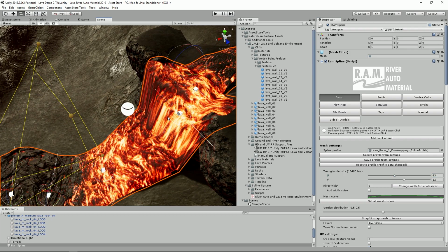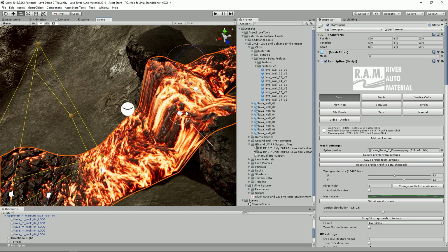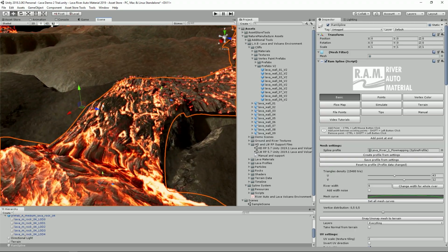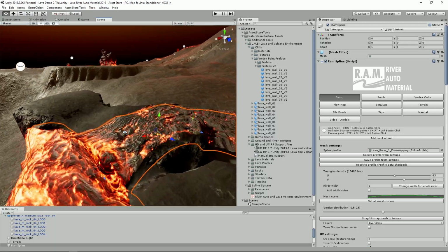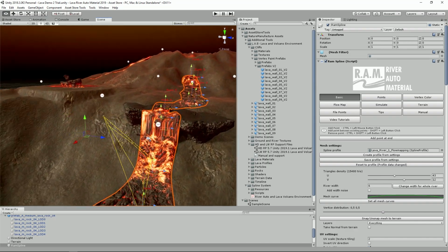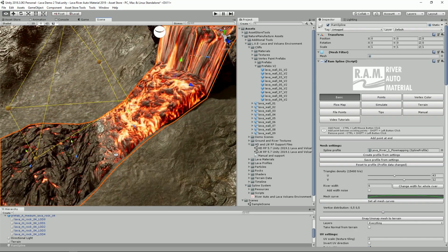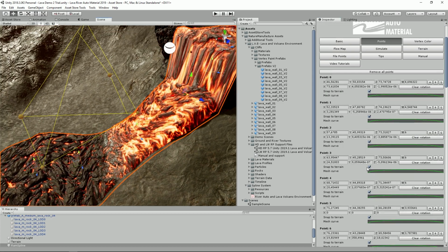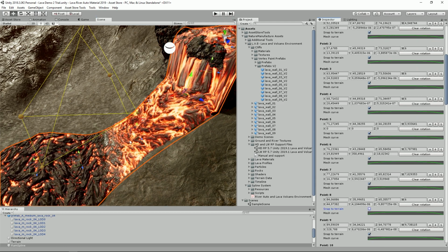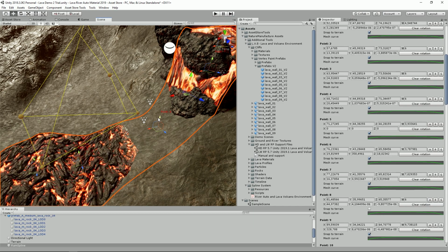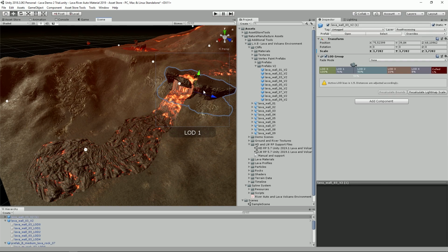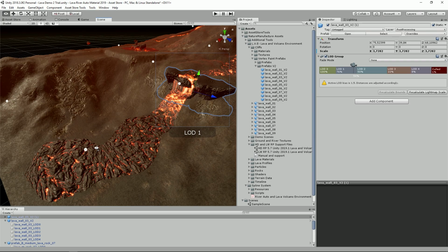Another option is to use spline curves per point, so you could manage the shape of the spline in the current place, so it will fit much better to the shape under the spline. It's a better way to do this. You will not add more verts, but you will have to adjust the spline manually. So as we see, we have many different ways to snap it into an object and make it fit with the background.